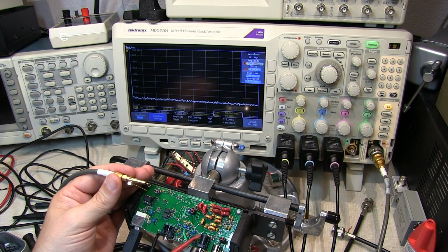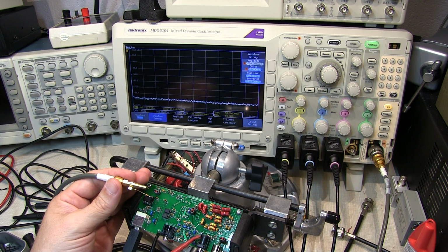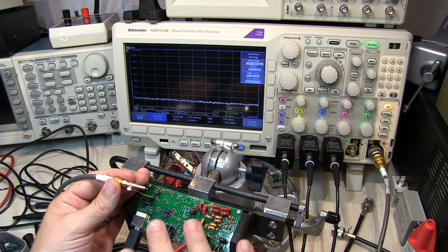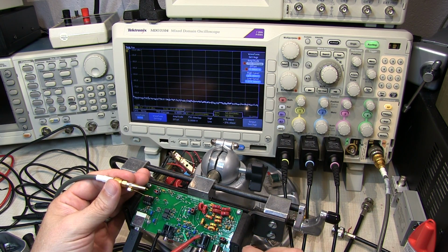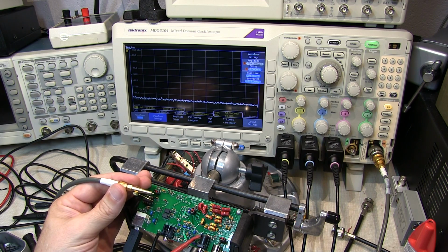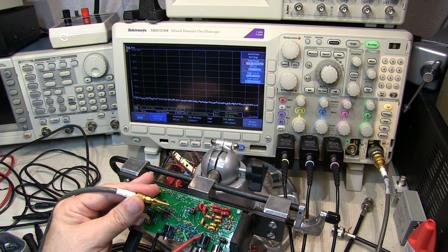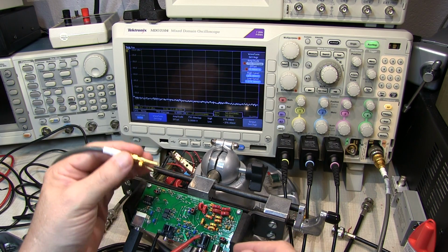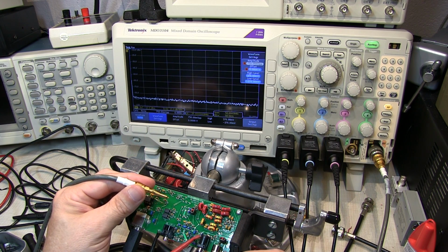To take a quick look at the bandpass filter characteristics, I'm putting a high frequency random noise signal, or a white noise source, into the front end of the receiver. That's going to give us a relatively flat noise power across at least 50 megahertz or a little bit more. So that's going into the input. We'll switch the receiver to operate at a frequency in each of those four bands, and take a look at the output of the filters right here, on the spectrum analyzer. Where I'm probing is very close to the clock, so I'm going to pick up a little bit of clock feedthrough here, and I'm not too worried about that. You'll see that.